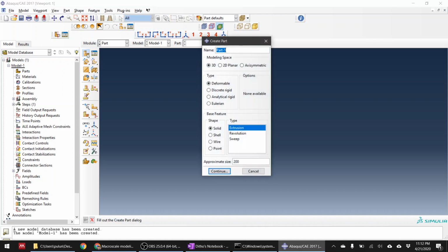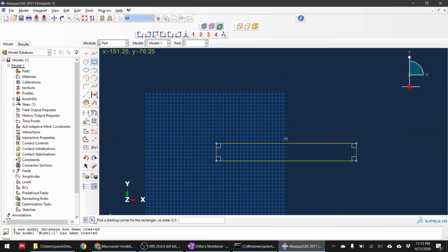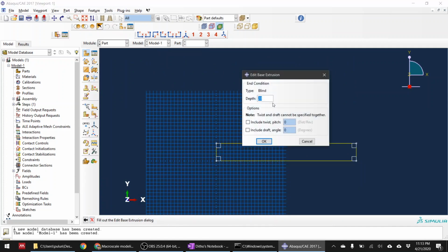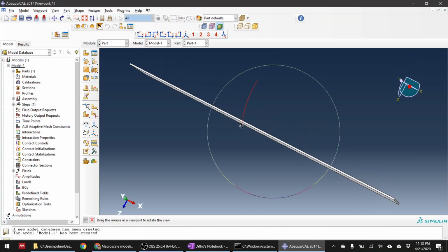I'm going to be fairly fast here because I already made other videos on my YouTube channel that show you how to do it very slowly. So let's do it very quick. Make it 0, 0, you can type it if you want, or you can click it. Now put in 200, 25 and click enter, then close it and click done, and then make it 1 millimeter depth. Okay, this is great. So now you want to make a partition.